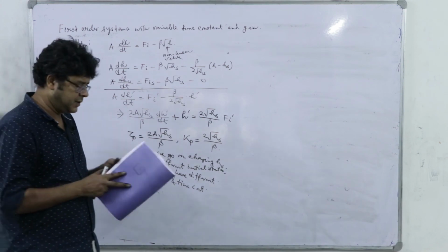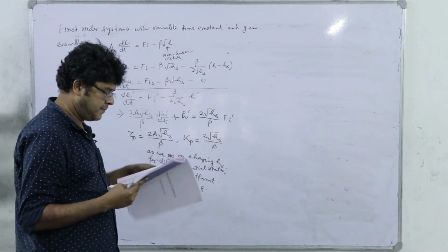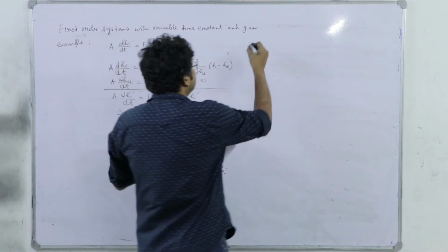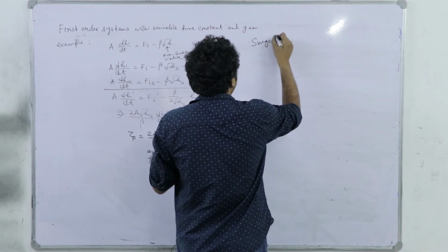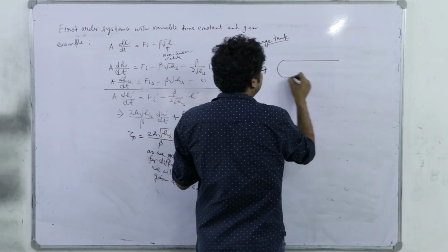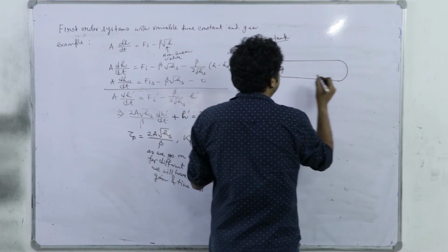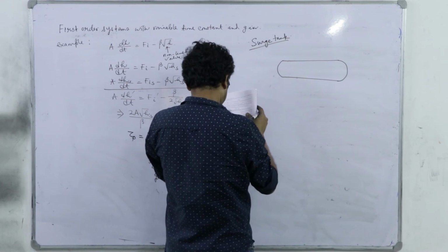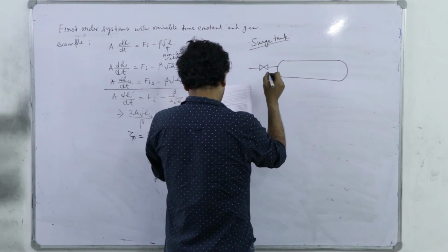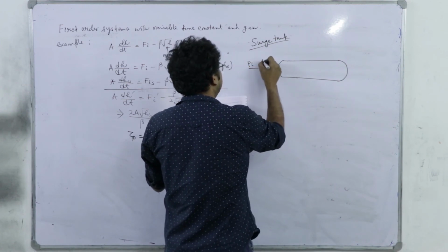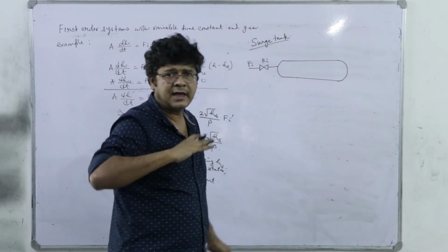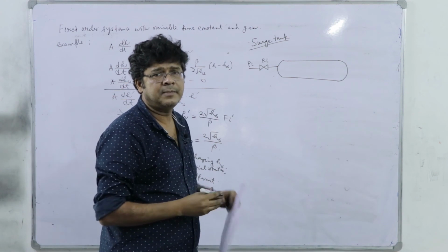So the last example we see here is called a surge tank. You see it is a tank. Sometimes you will see in process industry, particularly in a gas line, that we have a tank. That tank is not a storage tank specifically, but a surge tank. A surge tank is helpful in damping down pulsations, right? Say in a gas line, specifically a steam line maybe.